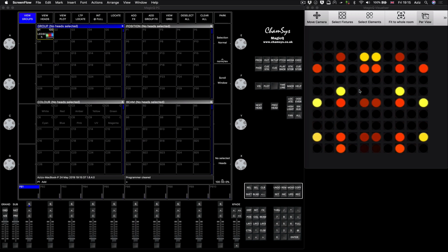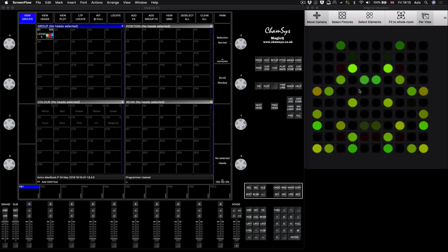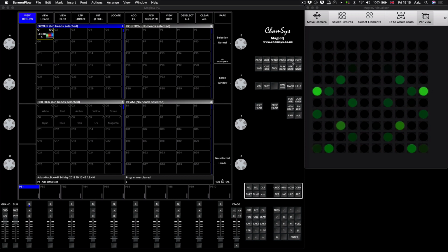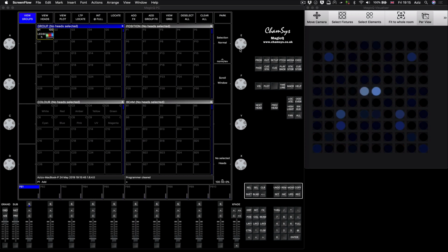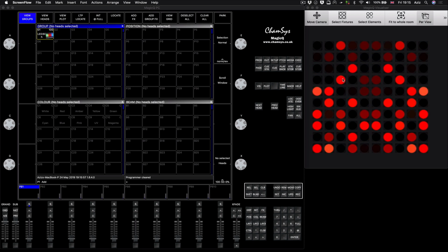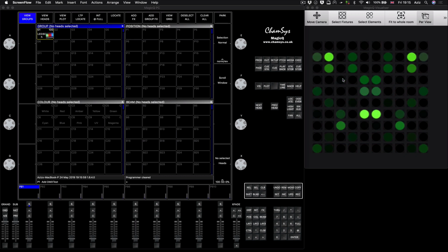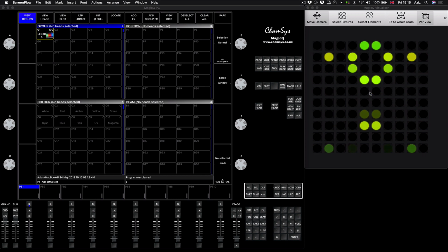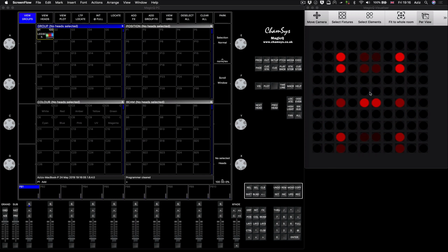Basically, I will show you from scratch how to patch, say, 100 fixtures, 100 RGB LEDs into the MagicQ, and make a wall out of them, a 10 by 10 grid. Then I will show you how on Resolume to create a fixture and send all this data from Resolume into the MagicQ, and this is the result you may get. I mean, this is the basic way.